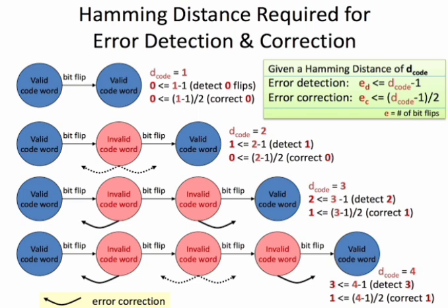The decoding algorithm may proceed as follows. For the received vector y bar, compute the syndrome S bar equal to y bar h bar transpose. Find the coset characterized by the syndrome S bar. Choose the error pattern with the largest probability, call it E naught bar. For output, that is for the corrected code word, compute the code vector x bar equal to y bar plus E naught bar.